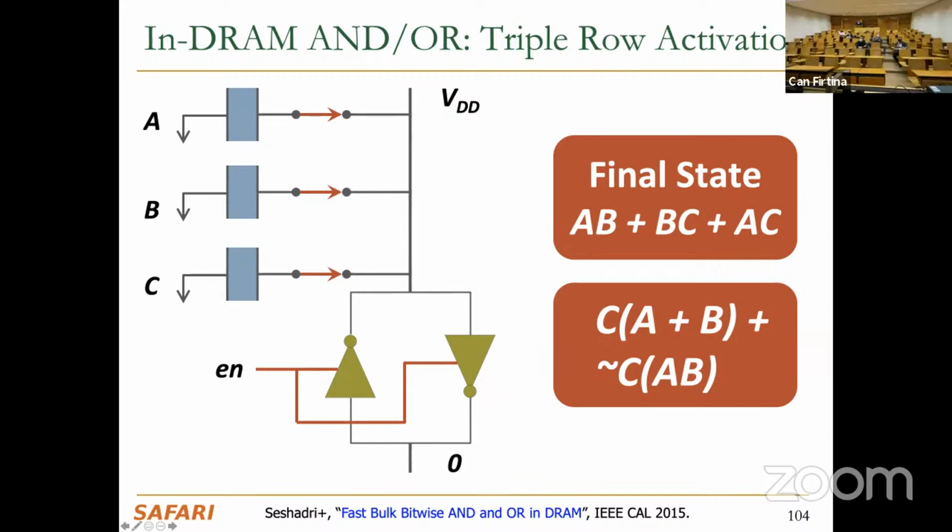So the decoders, what are they doing? They are activating the rows? Well, they're selecting the address of which row to activate. So you may have, for example, 1,000 rows in a DRAM subarray. You need to have a 10-bit address and decode it and select the word line, right? Yes, just a couple of AND gates, right?